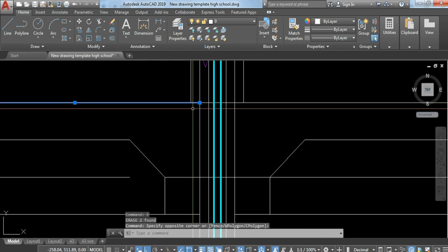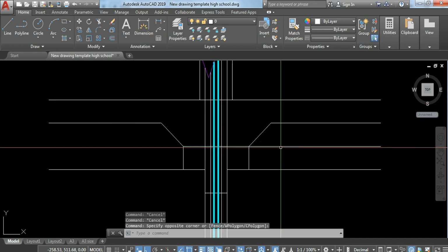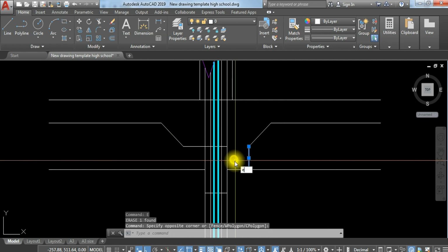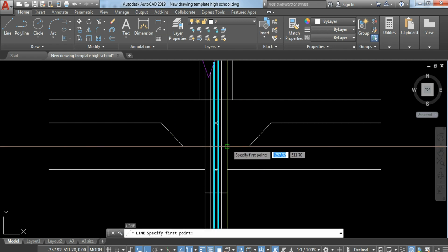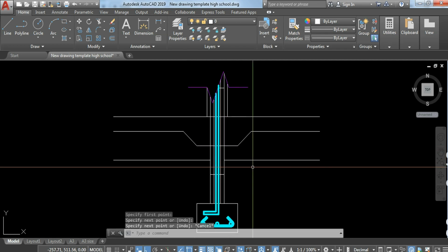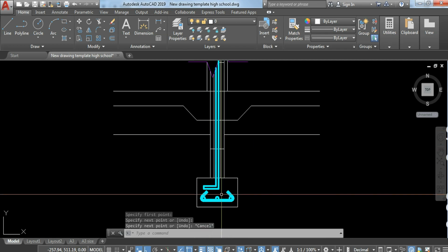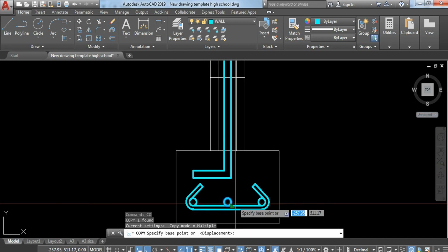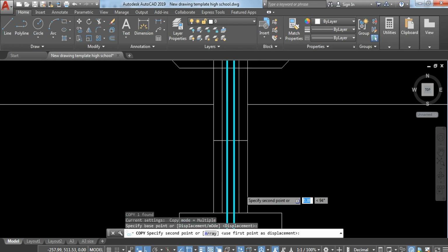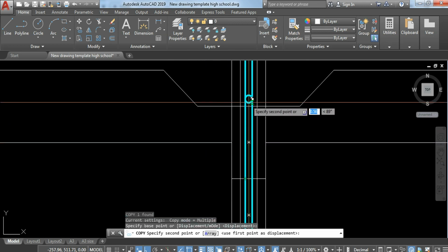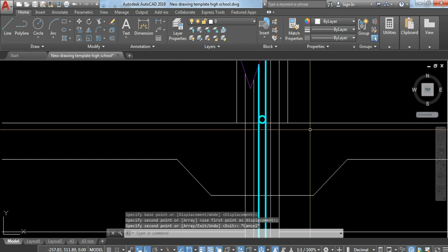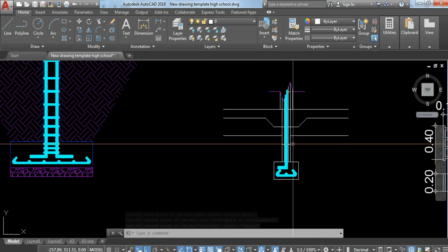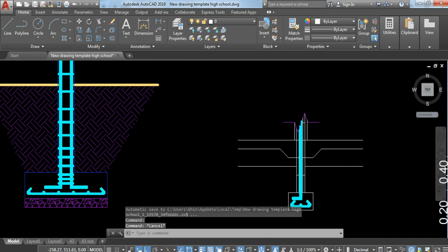Now that we already have these drawings here, it's time for us to also insert the steel bars. So remember, our rule here is that for every 3 layers, we have one horizontal steel bar that needs to be placed. Okay? So we have 1 CHB, 2 CHB, and then on every third level, we have a steel bar that needs to be placed.